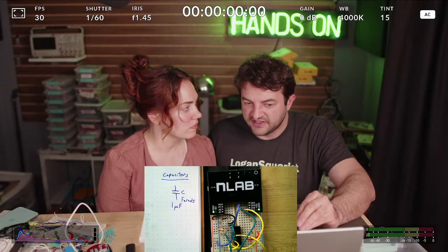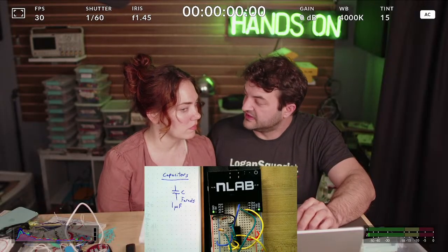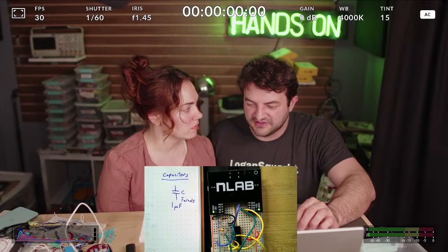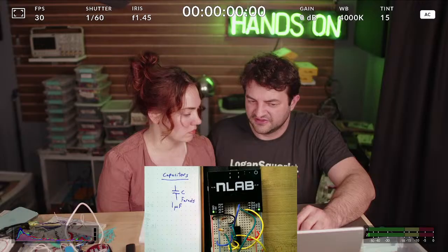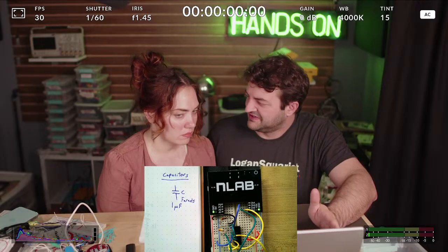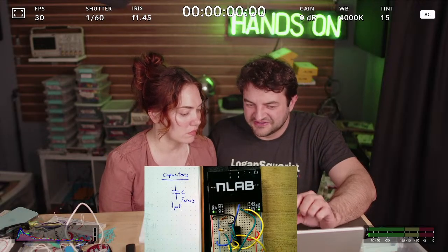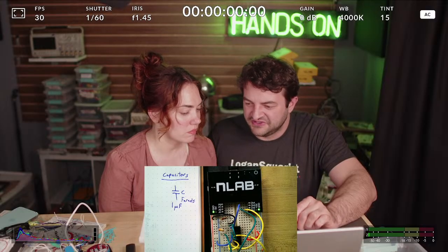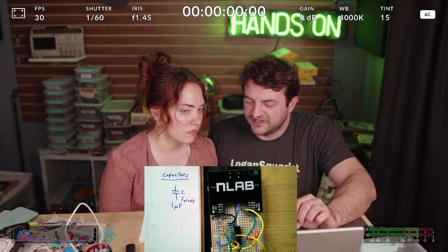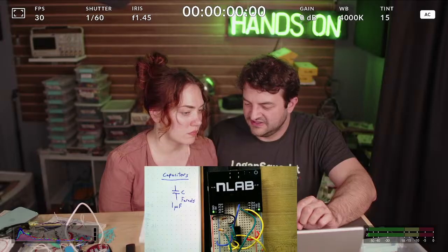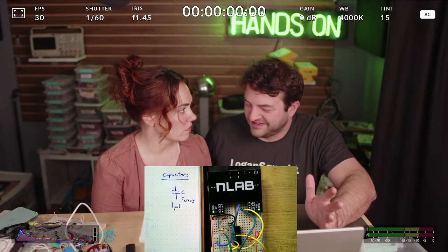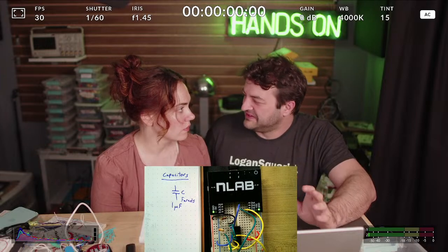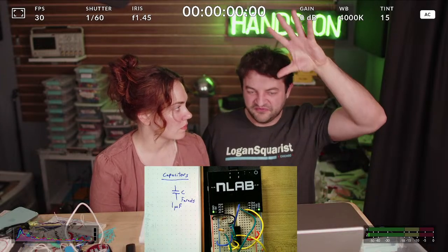And the battery wouldn't actually be capable of delivering 10 amps. So we usually write V equals IR assuming that the thing that provides the voltage is capable of giving that current. But that's not true. Like a little AA battery, when you short circuit it, you can only get up to like 3 amps. So the idea behind a big capacitor circuit in the flash, this is like nobody has this anymore, but you have this big bulb on top of the camera and go boom, flash.